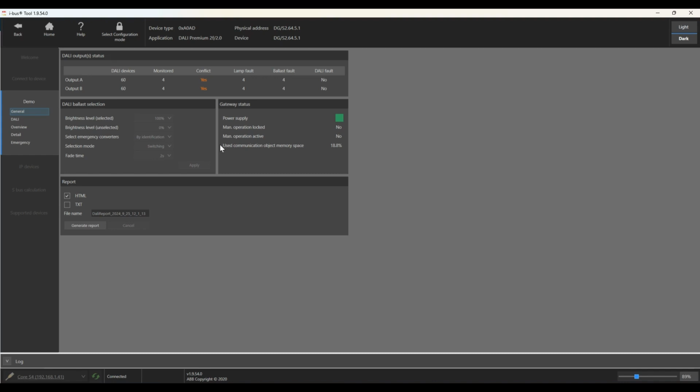A lot of people seem to use Rapix, which is a really good tool as well, and part of the appeal of the Rapix tool is that you can do it on a handheld device. For any of you that have done DALI commissioning, you'll understand what a big advantage this is, being able to walk around, turn lights on and off, and discover and readdress fittings like that. So hold your breath. I think it won't be too long before we'll see that come out.